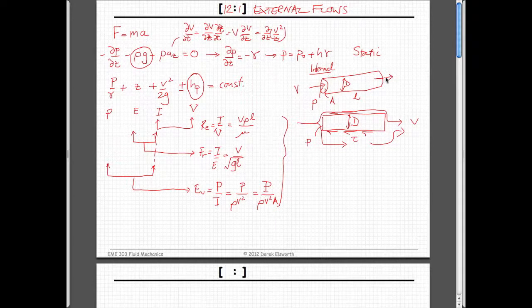So the question is, what links these two behaviors? They're very similar. One happens to be flow inside a pipe, and the other one happens to be flow outside a pipe. Of course, we don't really worry about that too much. If you think about the pipe as, instead of being a pipe, being the shape of an airfoil, then we would be interested in what the forces are that are applied on this. And so what we dealt with was that this magnitude of the power here, I suppose you could also write this as the head loss in the system, right? They're both equivalent components. And so what do we have? We have the head loss from pipe flow is equal to what? It's equal to friction factor, times some length over diameter of the pipe, and the velocity head, v squared over 2g.